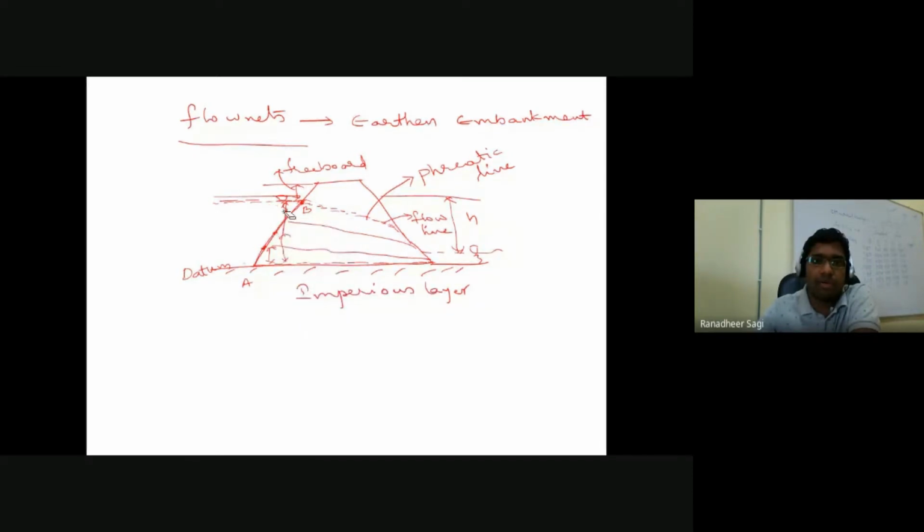I will be able to understand how to construct your flow net diagram by knowing what your first equipotential line is, or the equipotential line corresponding to your highest total head value. Once we know that, we'll go ahead in representing the other equipotential lines. So your line AB is one of your equipotential lines. I can say your line AB is an equipotential line.